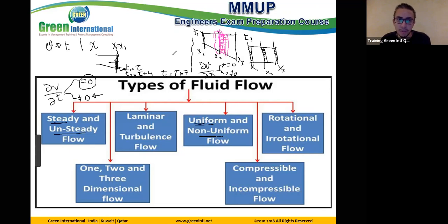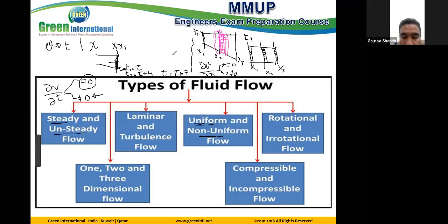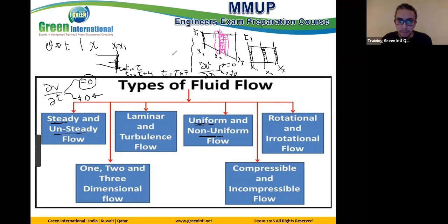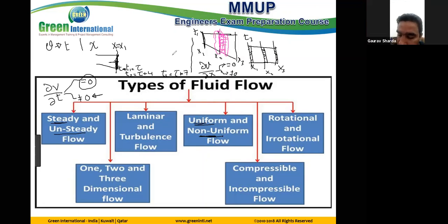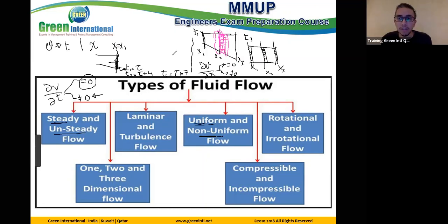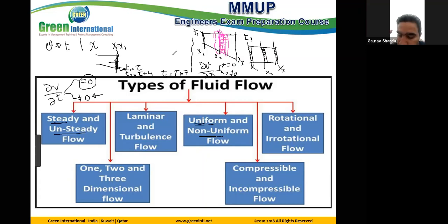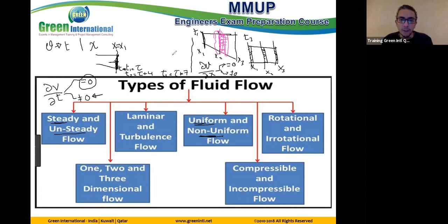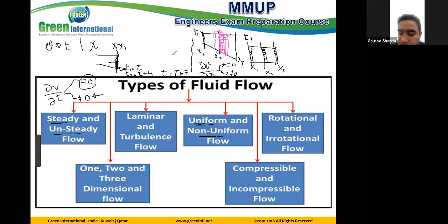And in uniform flow, you study with displacement, at different positions. But the time should be constant. It means for this pipe I will check the velocity at different positions at the same time, and for all positions it is the same. Okay, that's it.